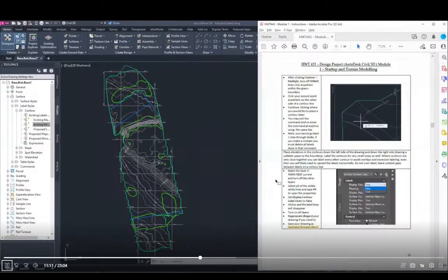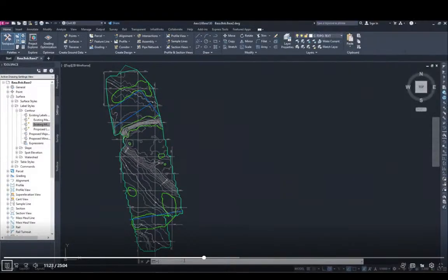Okay. Now, by the way, a little instruction that's in here. Sometimes you'll want AutoCAD to redraw the drawing for you, just to give it a nudge and make sure that it's drawn everything. So you can always type the regen command. You type regen, which is to regenerate. It just redraws everything just to make sure that everything's visible as it should be there. And I just did it there.